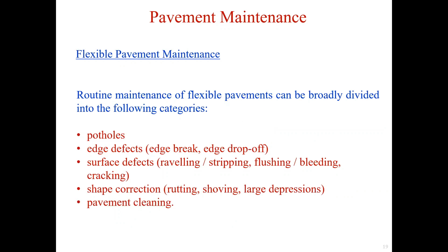Now let's look at the details of pavement maintenance, both for flexible pavement and rigid pavement. This part covers typical defects and repairs of bituminous surface pavement, which can be performed economically by a road maintenance crew. It is essential to maintain the road surface in a trafficable condition, so temporary repairs such as patching and crack sealing may be necessary, pending later resealing, rehabilitation, or reconstruction.